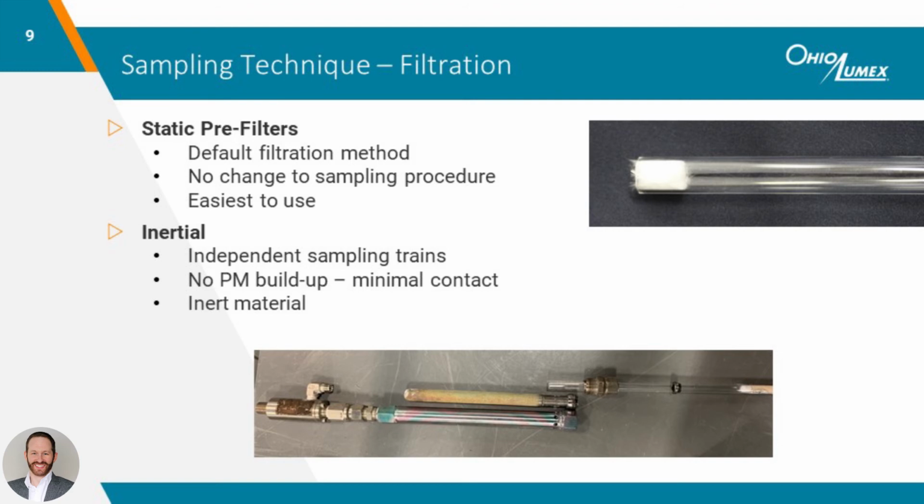filtration method to use. For locations with extremely high particulate matter, especially immediately downstream of a DSI probe location, inertial filtration may be required. Inertial filtration relies on the inertia of high-velocity particulate matter to separate particulate from gas. Essentially, each sorbent trap is fitted with a custom-made inertial filter and eductor. The eductor uses compressed plant air to pull sample gas across the surface of the filter at an extremely high